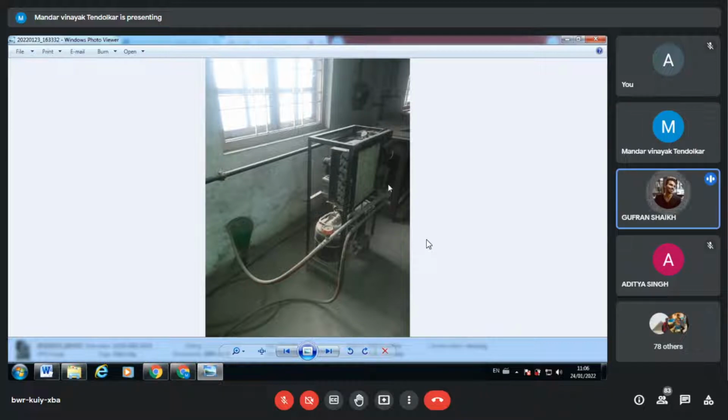Sir, if the pump is not working, why don't we use the same method in the video, like storage method? If the pump is not working for the flow of water, why don't we use the storage method, like they store the water and measure the temperature, right? You can do it. Nothing wrong in that. Whatever amount you will get, means the unit will be joules, not watt but joules. If I take m, that is total mass, I will get joules or kilojoules. If I get m dot, I will get watt or kilowatt.